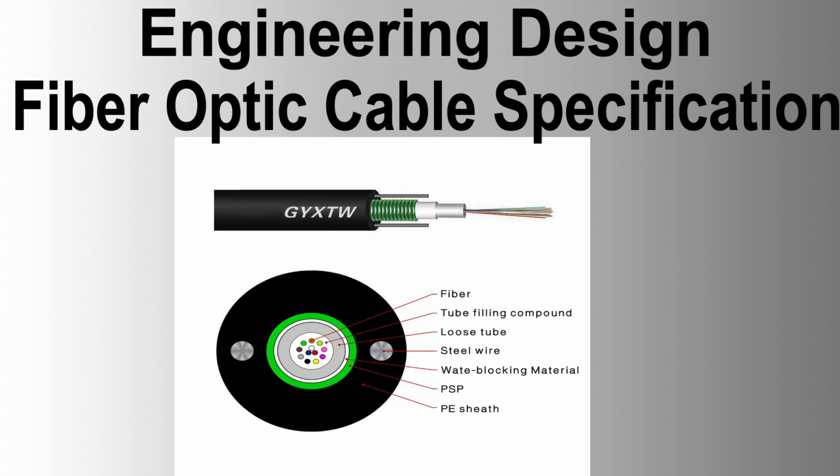HDPE conduit jointing requirements. Joining process. The contractor shall provide continuous cable conduit joints required at least at each end of the supplied conduit section. For critical areas, it may also be necessary to reduce the length of the conduit section to be jointed due to local criteria, such as topography and crossings.